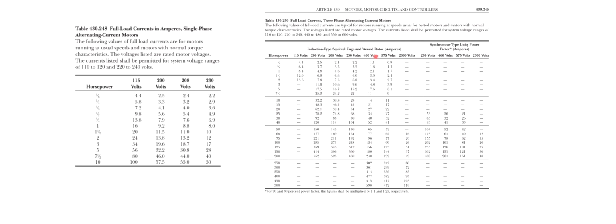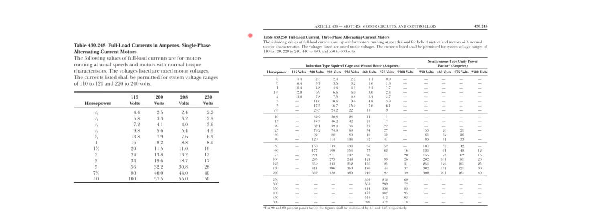Same thing. Your 480 volt is your 460. 230 is 240, 220. 115 is 110, 120. 200 volts, never seen it. 208 volts, they'll call it out directly. 575 volts, never have had to calculate for that. But that's where you guys find the FLC of a motor.